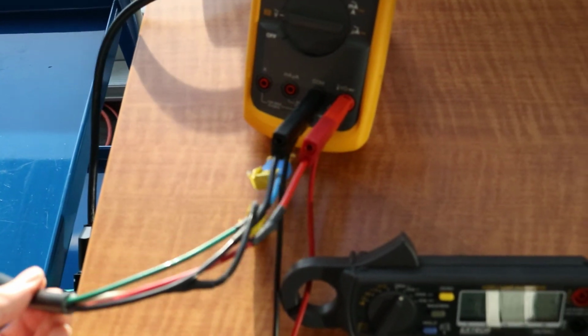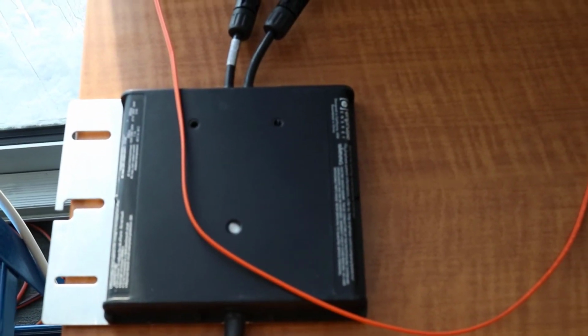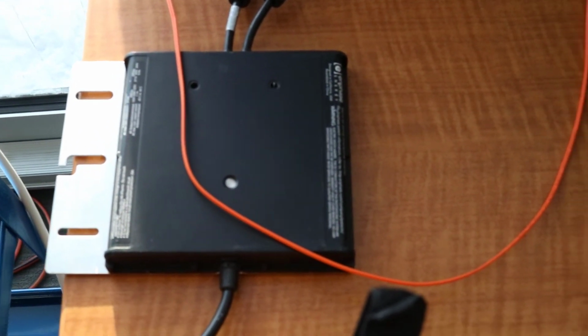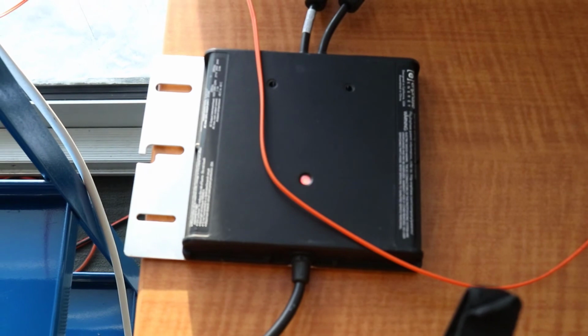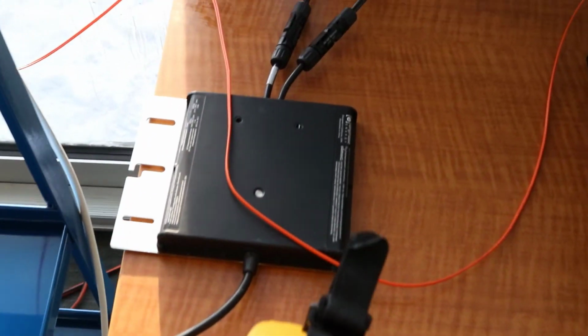So we can see that there's another connection to this meter connected to the output of the amplifier. And this is the AC side of the device under test, which in today's demonstration is this PV inverter. So we have the AC side of the inverter here. This is an inverter from Enphase, connected to the output of our amplifier, while the DC side of the inverter here is fed from our solar panel.